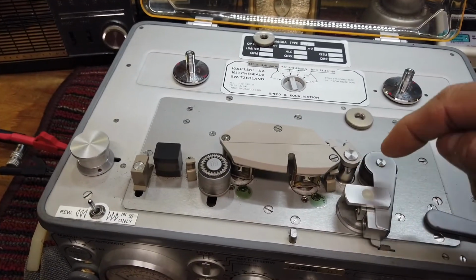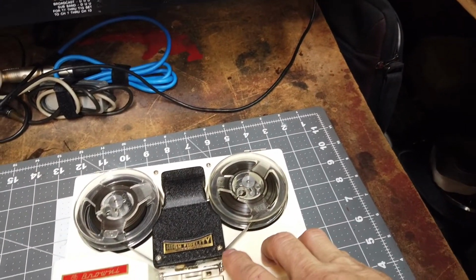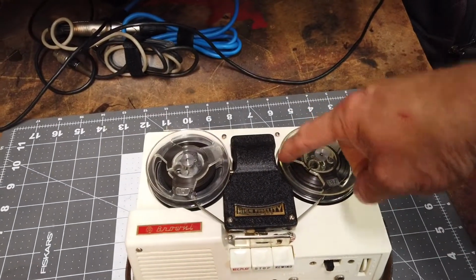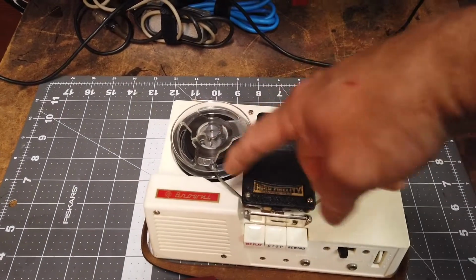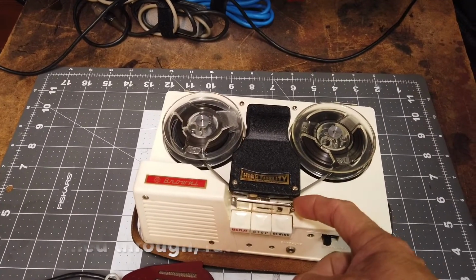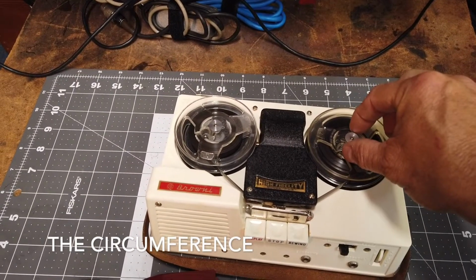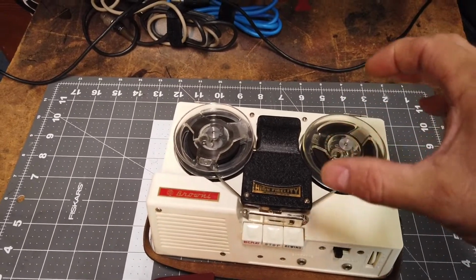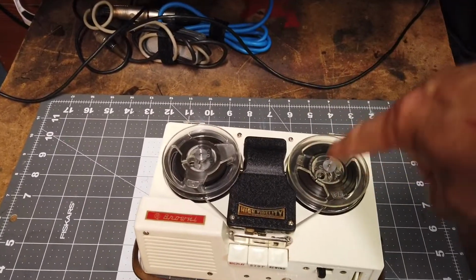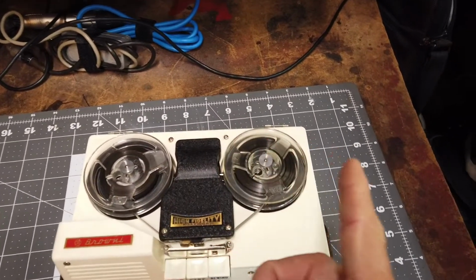This produces constant tape speed from the beginning to the end of the reel, whereas a non-capstan tape recorder, a rim drive, the tape starts slowly because it's pulling. This is pulling the tape through. It's not being pushed through with a capstan, and the diameter here is smaller, so it's pulling less tape through, and then as the tape gets larger and larger on the spool, it's pulling more and more tape through quickly, so the pitch changes and goes faster and faster.